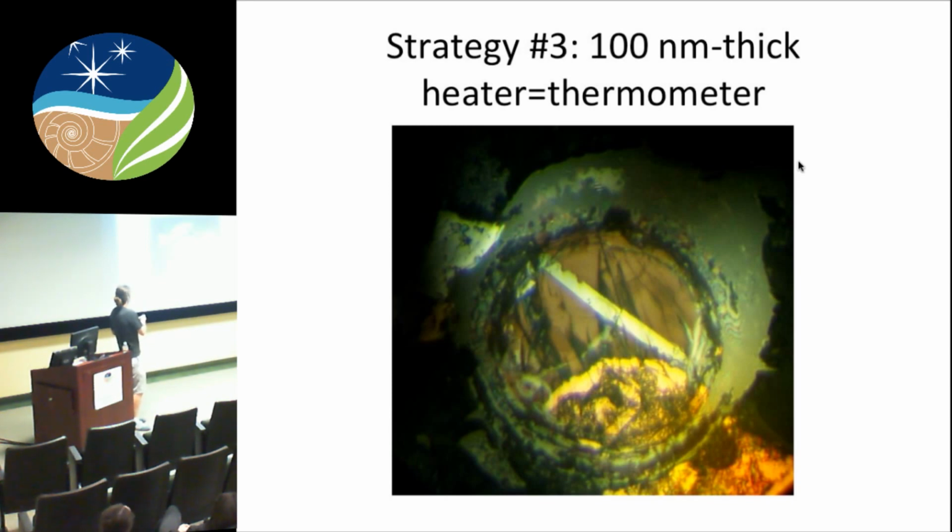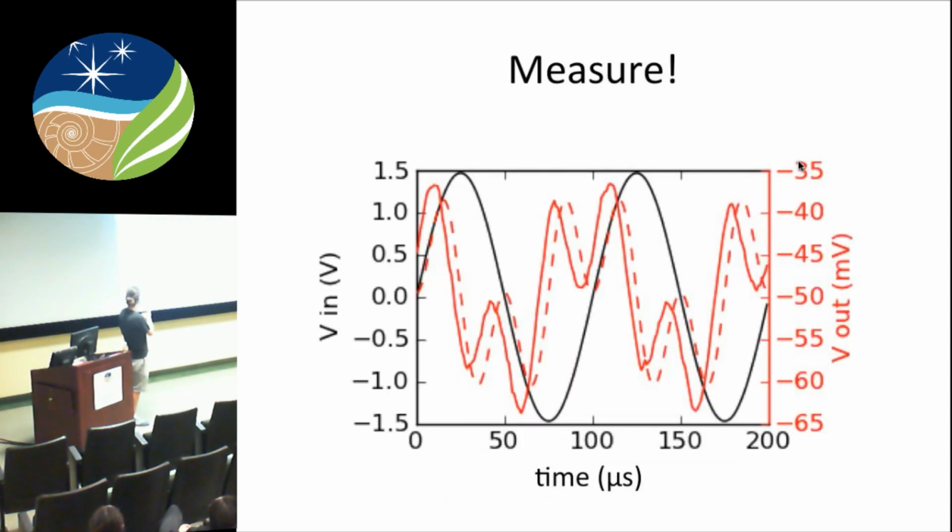So a better design than that platinum strip would be a really, really thin piece of platinum. Maybe I shouldn't try to explain why, but you'll see the data. So here's a thin piece of platinum that's getting pushed between glass. It's at 0 pressure, but there's good electrical connections. Pretty ugly, but the data looks good.